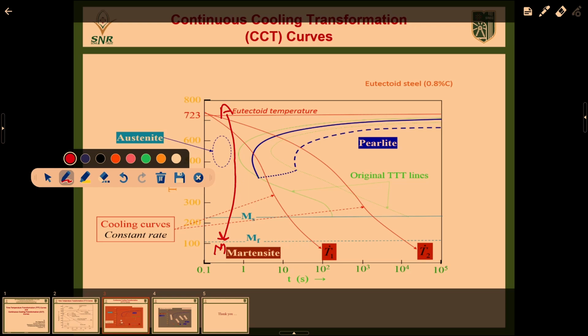Another thing, if you come to this one, you can understand this is 1, this is 2 and this is 3. For 2 and 3, we maintain the material in the furnace and use atmosphere cooling. At the transformation starting point Ts and transformation ending point, all the points meet and all the structures transform: pearlite, upper bainite, lower bainite and martensite. All of these happen in furnace cooling.